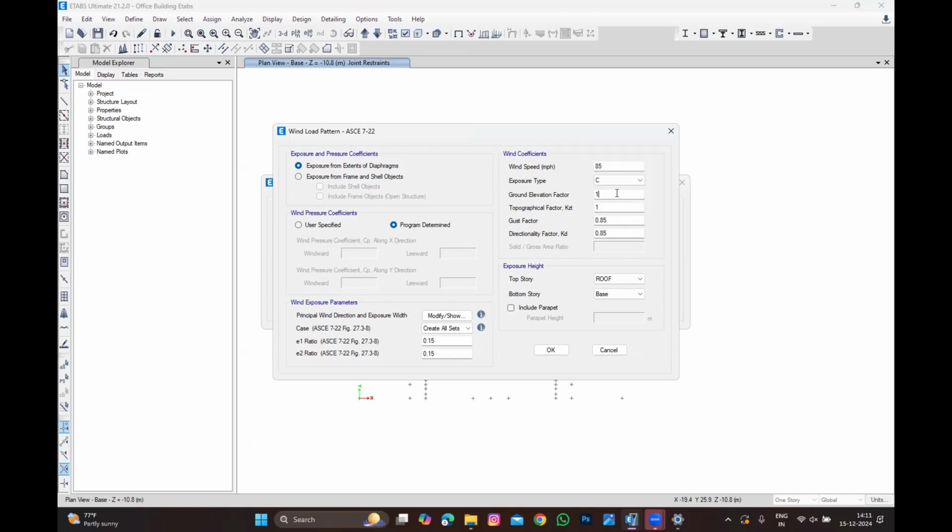It is recommended in the sense you do have some kind of solution, you can still go for it. It is advisable in the sense you still have some solution you can go for. It is not recommended in the sense you don't have a solution at all. Liquefaction, wherever you find it, you don't have any solution until you remove all the liquefaction soil.